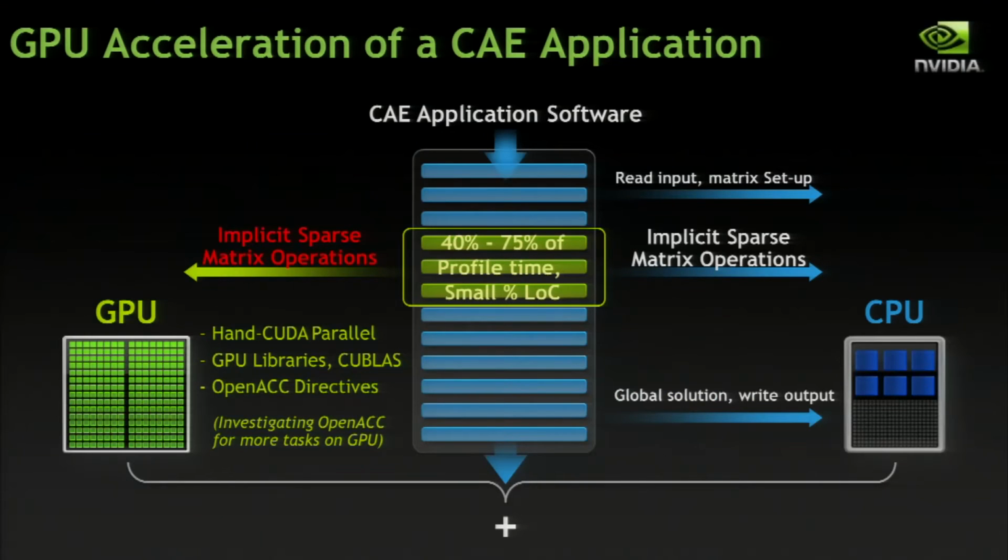What's happening in the background in a CAE application? How are GPUs accelerating it? Take any simulation such as CFD, for example with an implicit solver. The steps are: you have a mesh that you pre-process, then you do discretization, then there is a linear solver portion, and then the solution update portion.